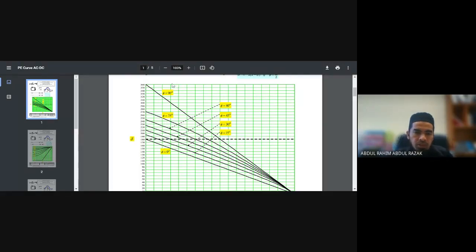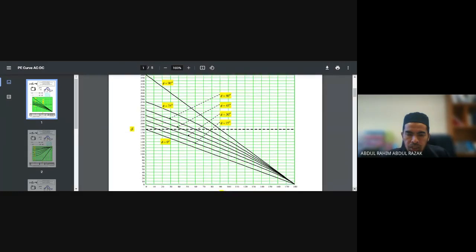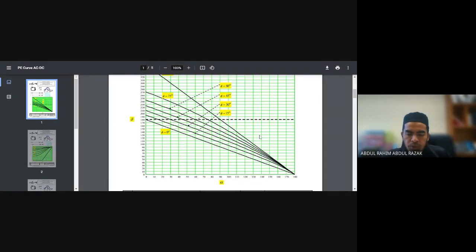When inductance dominates, the load angle will be around 90. So different load angles will produce different extinction angles. And this extinction angle also later on will determine how much your safe alpha you want to set. And that one we will discuss later.